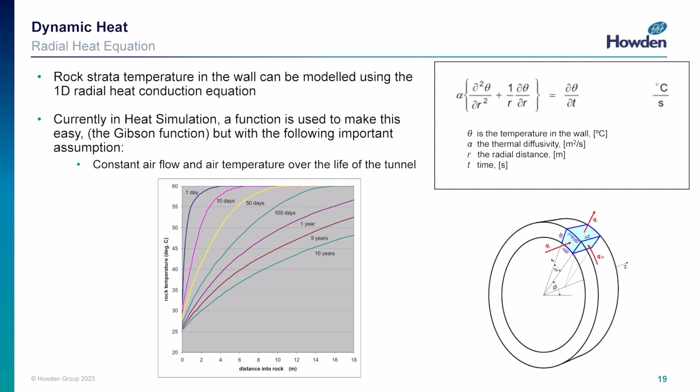So basically what I've set up here, you can see this graph at the top. I've got a graph of temperature on the y-axis, and the red line is showing the temperature into the wall. So at the very left-hand side of that graph, I'm at the interface of the air with the rock. This is a freshly dug tunnel, so everything is at the VRT, which is currently 41.6 degrees. And I've got a blue dot here, which is giving me the temperature of the air. So let's say that this is some cooled air. Say it's 15 degrees. And I'll just set this off.